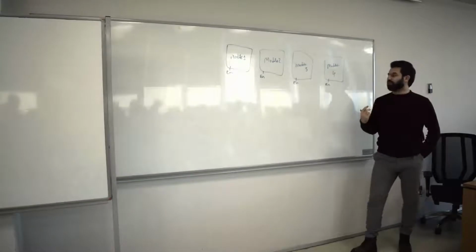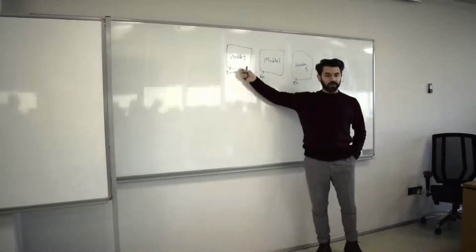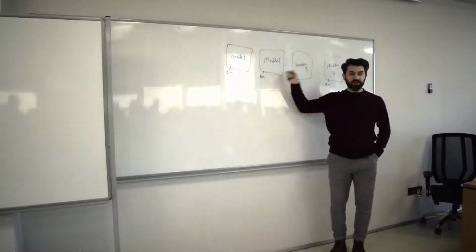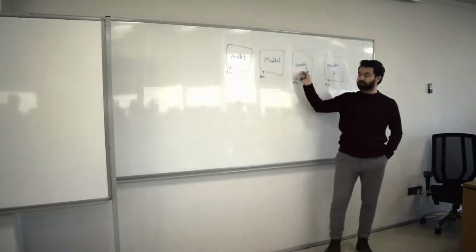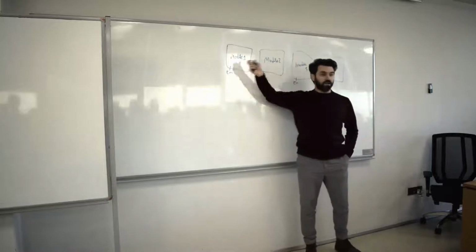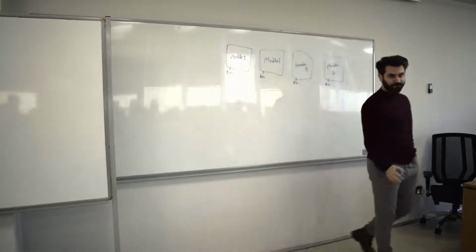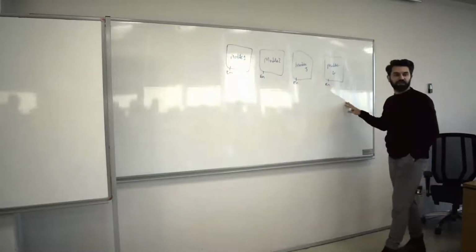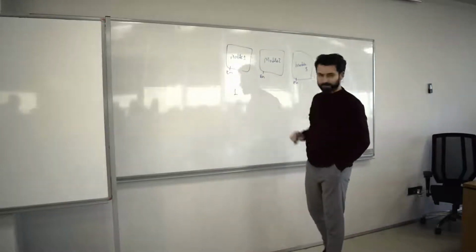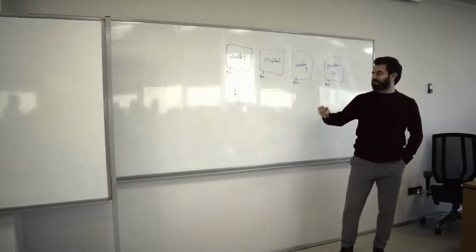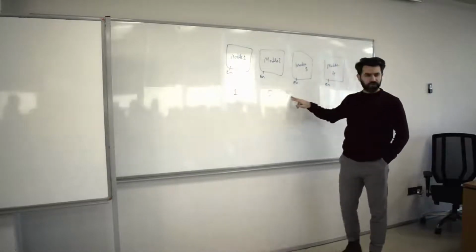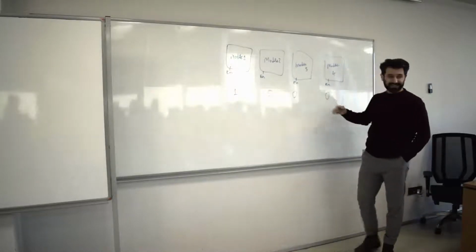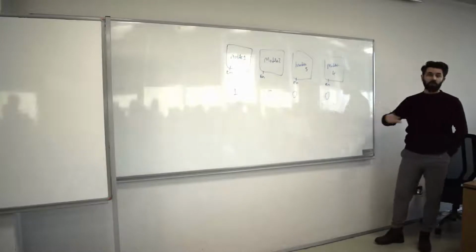What I want to do is first enable module 1, then module 2, then module 3, then module 4, and then back to module 1, then module 2, module 3, module 4, and back to module 1, and so on and so forth. That means I have to generate a 1 here, a signal saying it's a high logic value, and a 0 here, 0 here, 0 here, at a specific time instant, which I'm going to call a period.